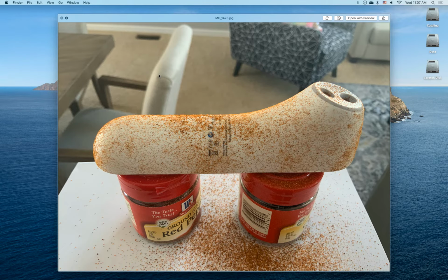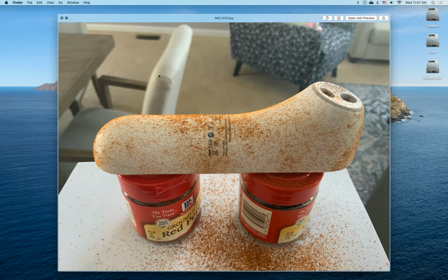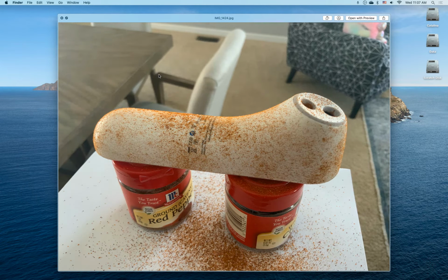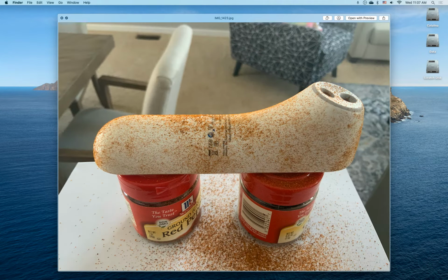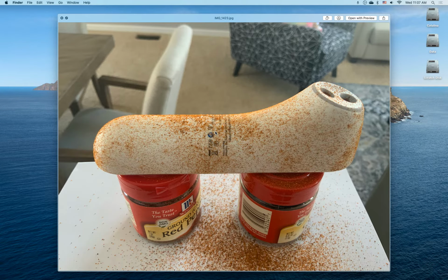And before we jump into MetaShape, this is how 3D photogrammetry works: the software takes a look at this image and tries to identify features, here very easy to identify ones I could memorize. And then I go to the next image and do the same and then compare. So here and here, where do we find matching elements? Now, for example, let's focus here on the triangular warning sign, where it is in each image. So there are 3 positions in the image.